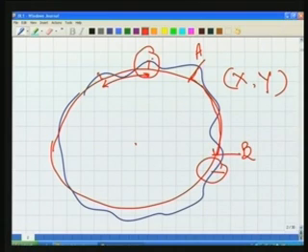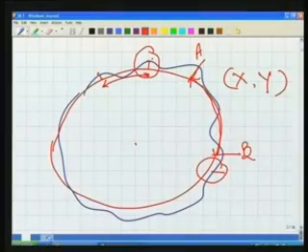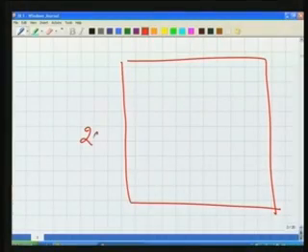But of course, the distance between the points A and B should be measured considering the curvature of the earth, because this is how physically they are. But this is true only if we are talking about a very large extent, a large area. This is not true if the area is very small. So for our engineering surveys, our areas are generally smaller. You know, an engineering project, for example, let us say if it is 20 kilometer by 20 kilometer,